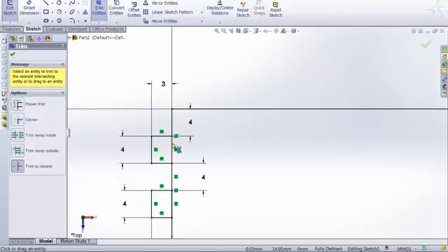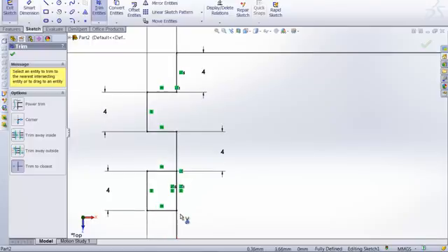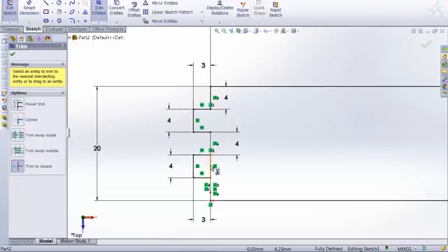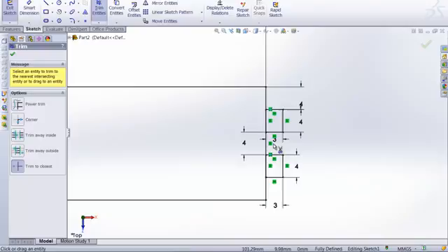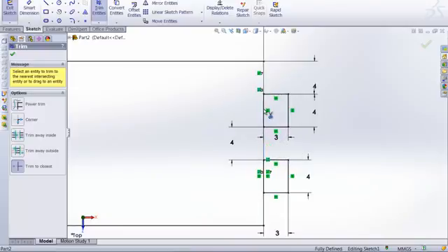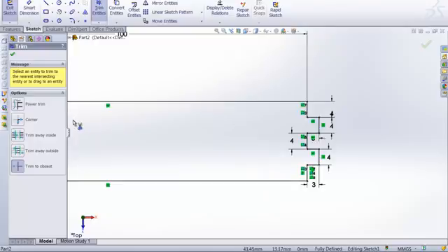I'm going to cut off. Well, remember, those are 2 lines actually together. One is from the big rectangle and one is from this little tooth. So I'm going to click once and click again to get rid of that. Okay, so I'm going to click once and click again to get rid of the other line. Now I'm going to zoom out. I'm going to zoom in here and do the same thing. Click once, twice, once, and twice. And my shape is still fully defined, which is very, very good.